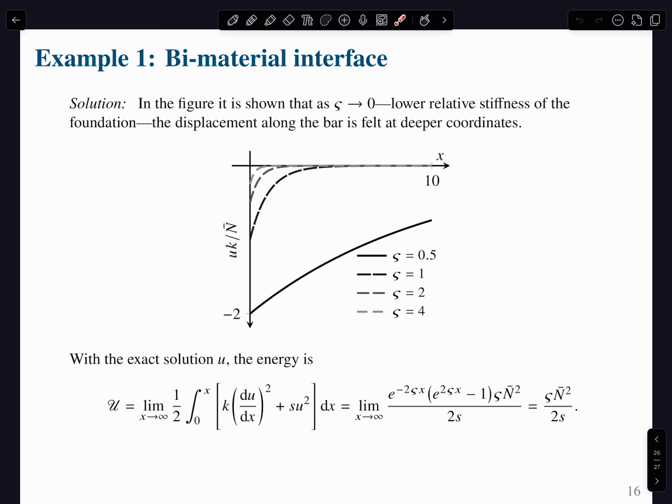Why? Well, because we know that the finite element approximation is picked to be the best of a certain space of functions. Would you then, in the element, have both a linear function and the exponential function? There you go, that is what we do. When we say we enrich, normally we don't touch our partition of unity shape functions, our standard finite element space, the linear space. We just leave it. But we add something extra.